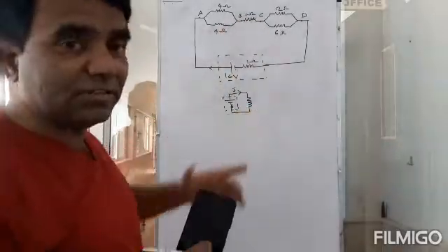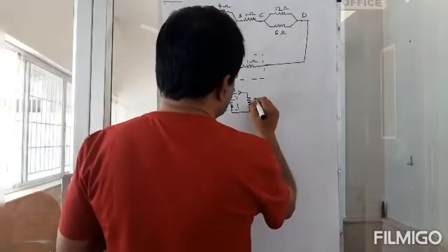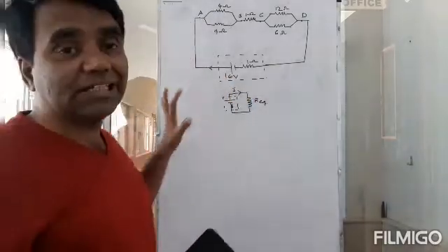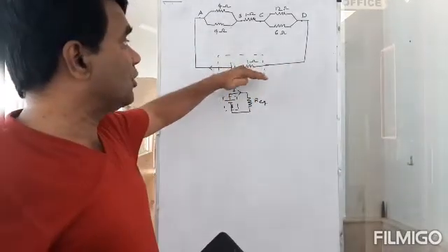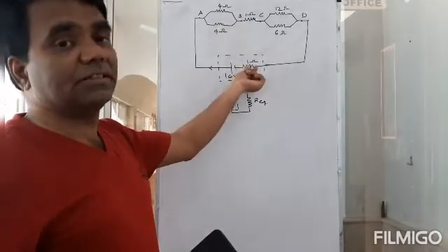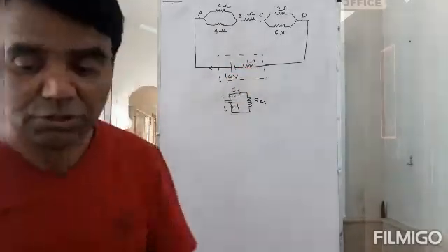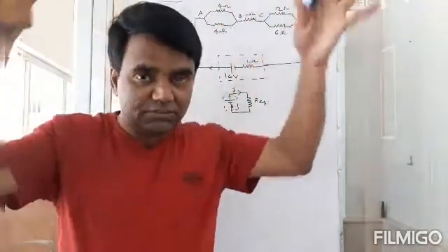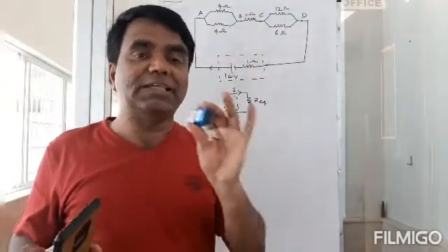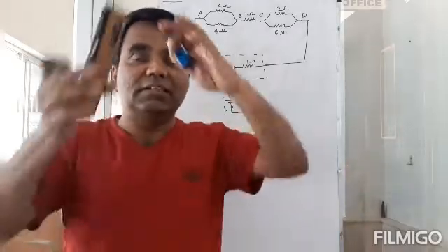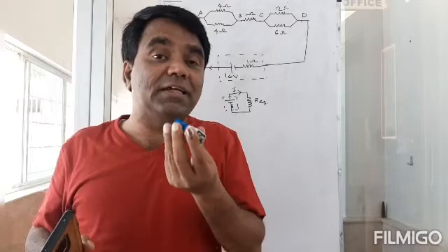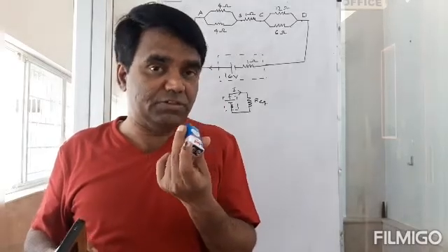So that is actually the equivalent resistance. Okay? So when you calculate the equivalent resistance, you should not be considering this resistor at all, because it is internal to the battery. So this is not part of the network now. I can replace this battery with something else, right? Then the network still remains the same. Okay, so that battery may have a lower internal resistance.